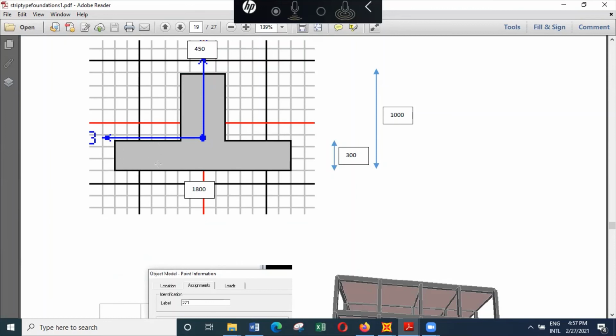So direct shear occurs here due to the loads acting in this area. So the outstand is 675 millimeters and the effective depth is 252 millimeters. So over a width of 423 millimeters, you get a load of 140 kilonewtons. So you get a shear force of 59 acting here.